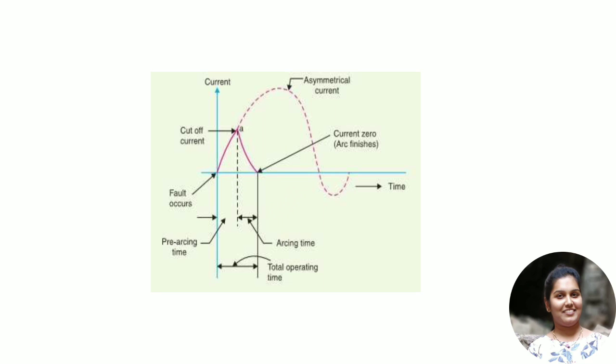So the current rating, fusing current, pre-arcing time, and cutoff current values should be known when dealing with fuses for any application.